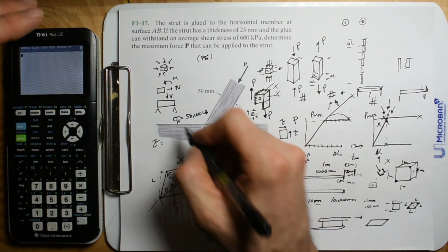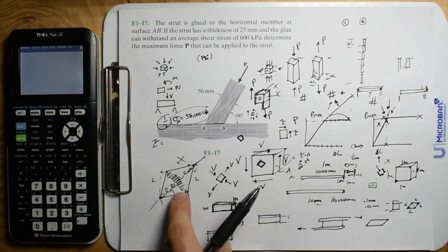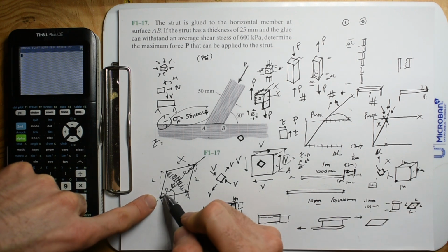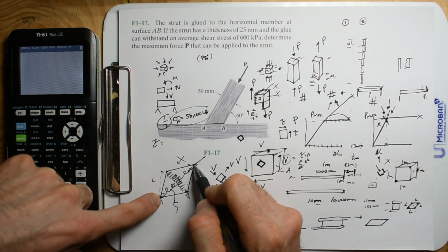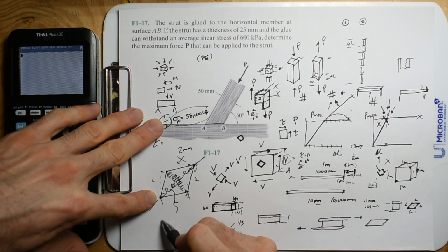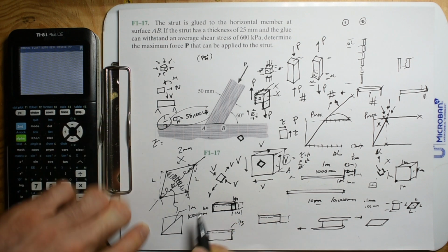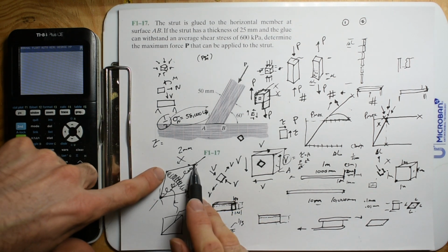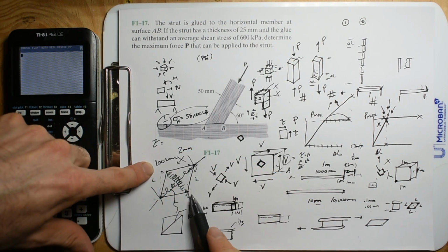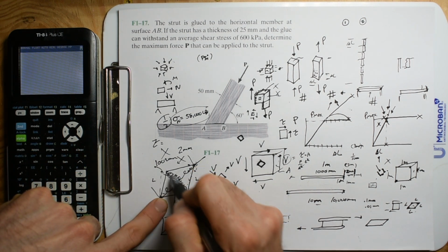Well, it's about half. It's going to be about half this number. And where does that come from? Well, it comes from this. I'm going to go one step farther and say, if any 2 points get farther than 2 millimeters away, so if this distance was 1 meter or 1,000 millimeters, and then I turned it into this shape, and this length got to be 1,002 millimeters, well, that's when this breaks, and these bonds break, and we get a break at a 45.